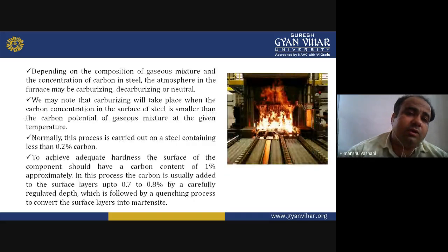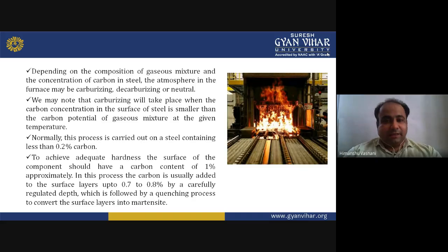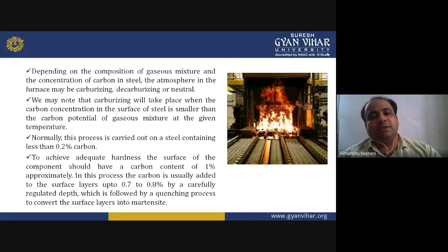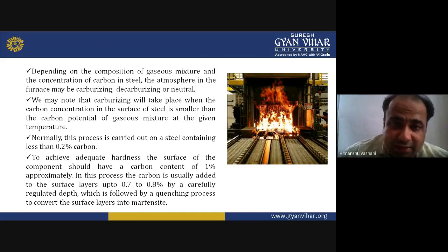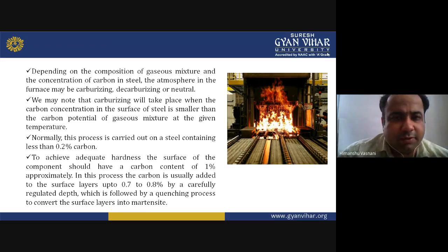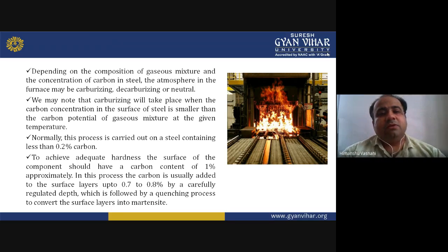Now, depending on the composition of the gaseous mixture and the concentration of carbon in steel, the atmosphere in the furnace may be of three types: carburizing, decarburizing, or neutral.